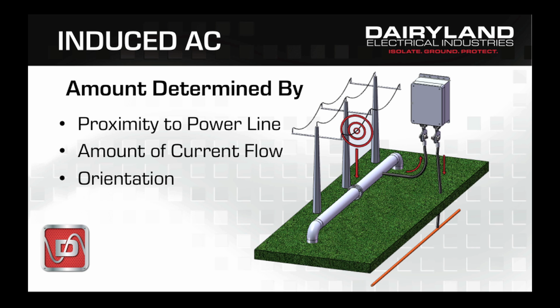As we looked at previously, and we'll review again in just a minute, some of the DAIRYLAND decouplers are not rated to deal with induced AC conditions because they will actually trigger into conduction and will stay in conduction continuously, a mode they are not designed to operate in.